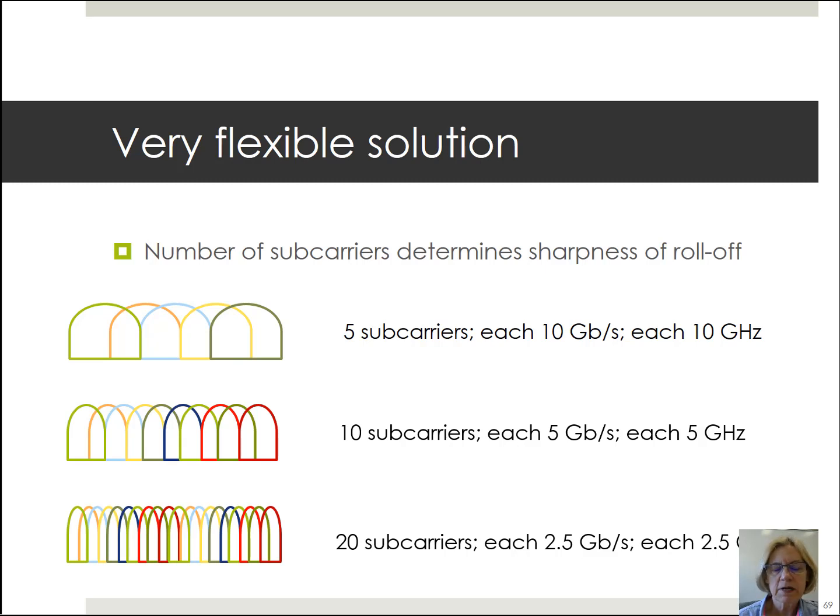And these impairments could come from equipment, could come from the propagation, the transmitter receiver equipment, it varies. When I do an equalizer, the faster the transmission, the more complex the equalization, because my digital signal processing has to be running very fast. For instance, suppose I had a single carrier system at 50 gigahertz. I would have to have my digital signal processing running at 50 gigahertz.